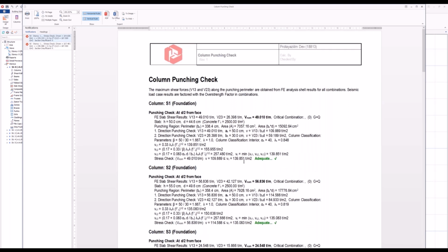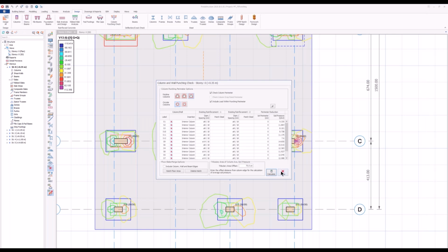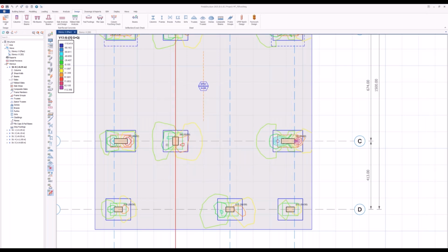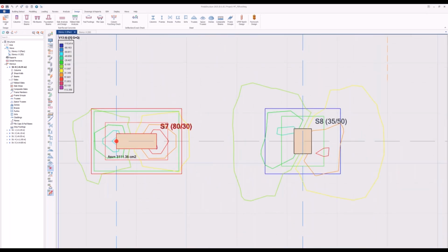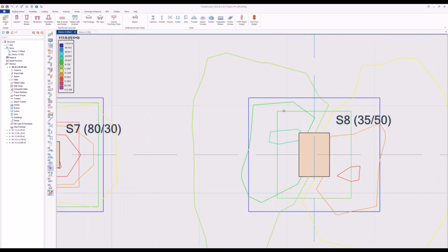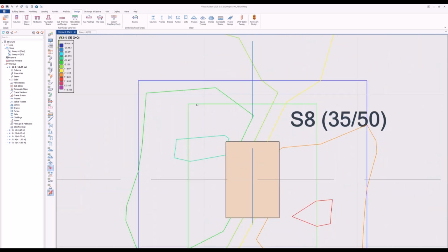So in codes there are different formulas, and also if the punching stress, the tau, is greater than the cracking stress, you have to calculate some reinforcement, etc. And also you have to check the consecutive punching perimeters until you satisfy the conditions. Anyway, there are some details on that. Let's close it. As you see, we also show the punching perimeters here in the blue, the green color.